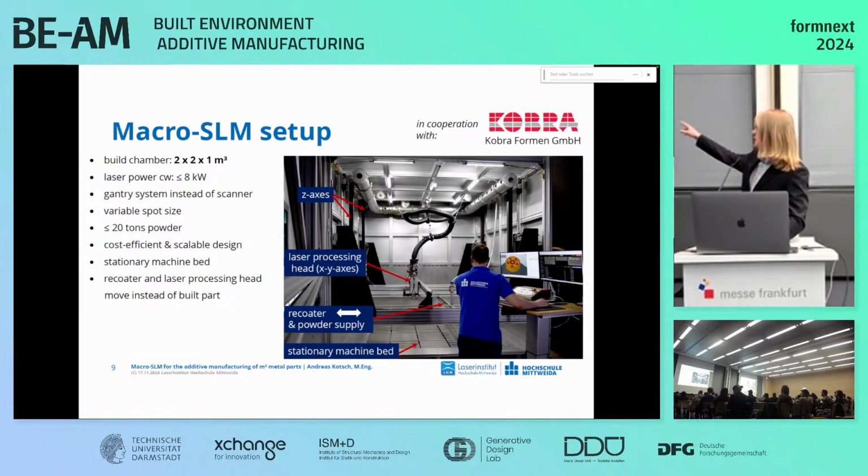So you would have seen in the video how the laser machine is moving around. And then the recoater first is applying the powder layer, which is about, let's say, 1 millimeter high, so very, very large. And then the laser head is moved by the XYZ axes across the sample to treat a part, and then the next layer is applied, and then the process is repeated. So let's move on.